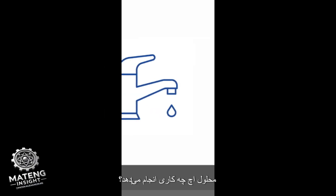What does the etchant solution do? Etchant solution is an acid. When we put the specimen in it, the parts that have more energy burn and their color changes. So, this color difference allows us to see the microstructure under the microscope.